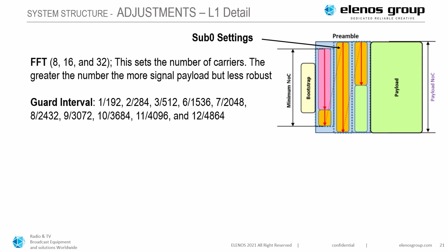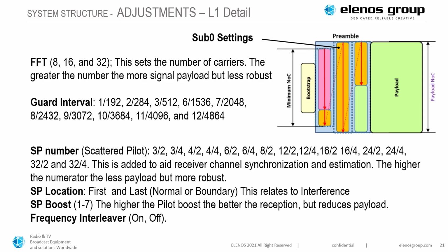Then we look at L1 detail. Now it's getting a little bit more complicated. You have to choose the FFT and the guard interval. And you have to, again, select the number of scattered pilot patterns.